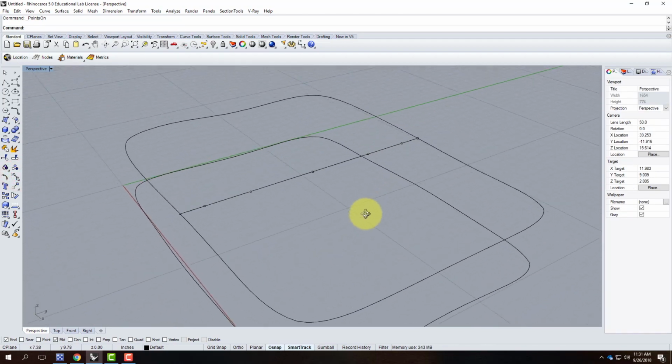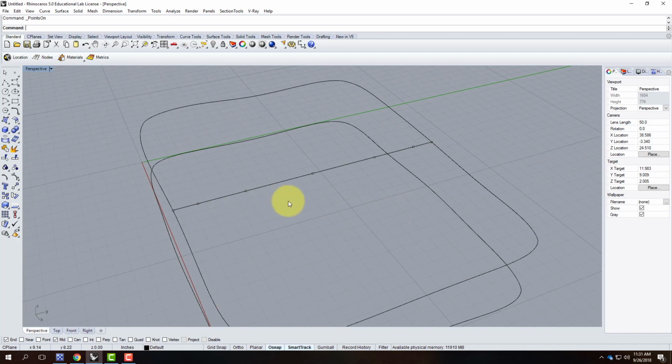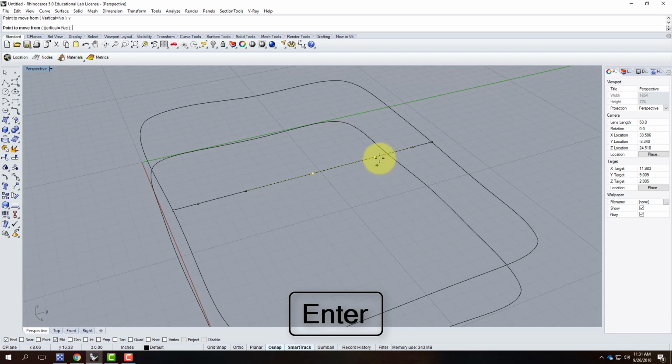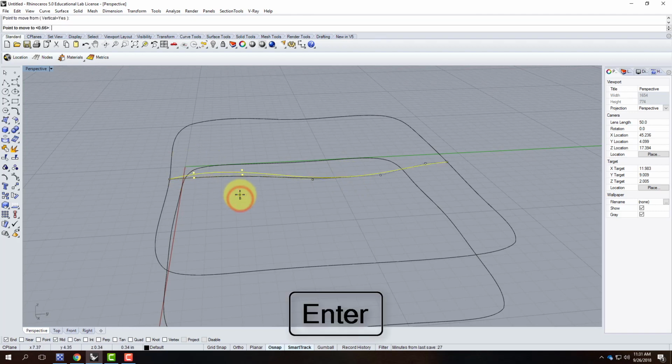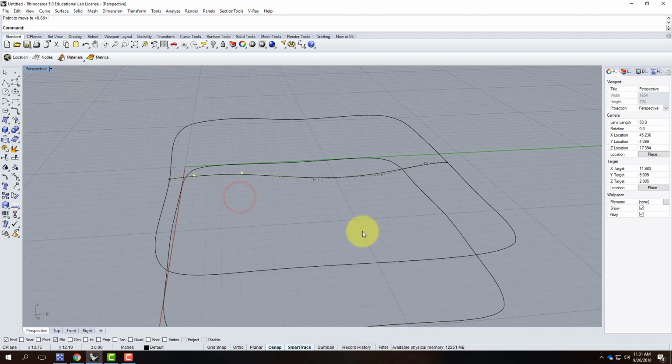So let's say that this seat is a little bit worn, and we've had a lot of people sitting in it. Well, chances are the back part of the seat would have a little bit of a depression where the stuffing's been smushed down a bit. So I'll take these 2 points, there and there. I'll move them, V for vertical, and we'll drop them down a little bit, maybe like that. Maybe the stuffing's a little bit overstuffed here because the stuffing has to go somewhere. So maybe we'll push these up just a little bit. Move, V for vertical, and we'll push those up just a bit. A little too much. Maybe like that.